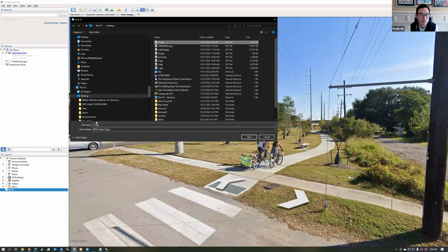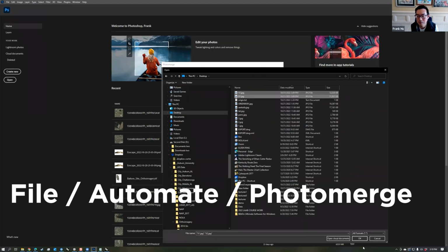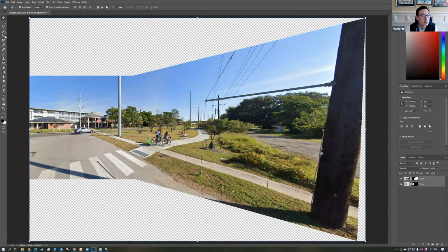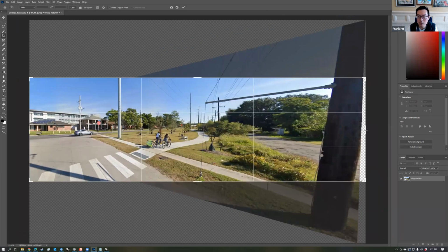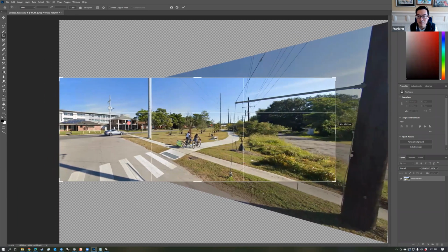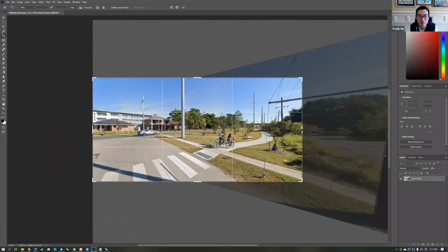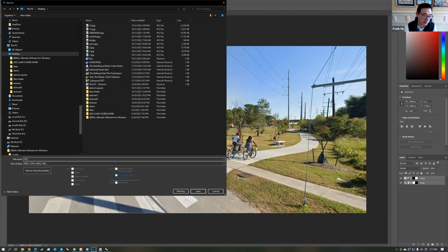Save image, view 2. So you go to Photoshop, automate, photo merge. So what you would do in this case, we just simply trim this to be a simple perspective. There's a portion of this where the perspective gets a little bit out of hand, like right around here. This is where I might cut it off. So we'll save as AS for Aaron site, Pano.